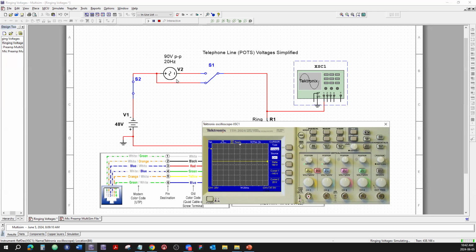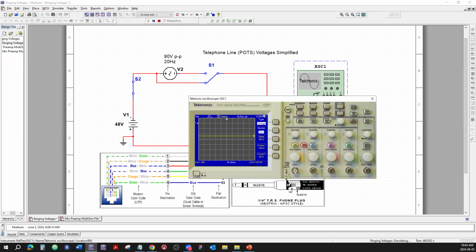No. Most of the time it would be that maybe there's a new model of that ATA adapter, and somebody didn't pay attention to provide exactly 90 volts minimum, or the current capability for the paging interface to be powered. So sometimes you're going to have some weird problems like that. I'll tell you more when we go further with the theory classes.